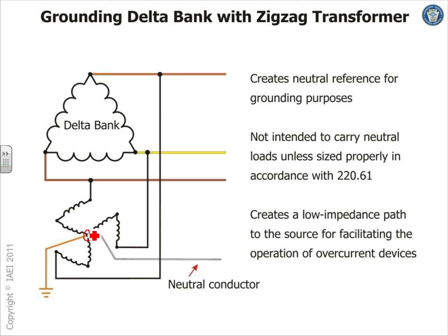So what is a neutral point? You take phase A, phase B, phase C, and add them vectorially, not algebraically, as vectors. When you add them up, if the system is balanced, what do you get? A big fat zero. So that's how they do it. They create the zero point, the neutral point. If you create a zero point, pull a wire and call it neutral. So that's how you can get a neutral on an ungrounded system, right? And you get your 277 lights or whatever. That would be a solution for an existing problem, not a good design for a new building.